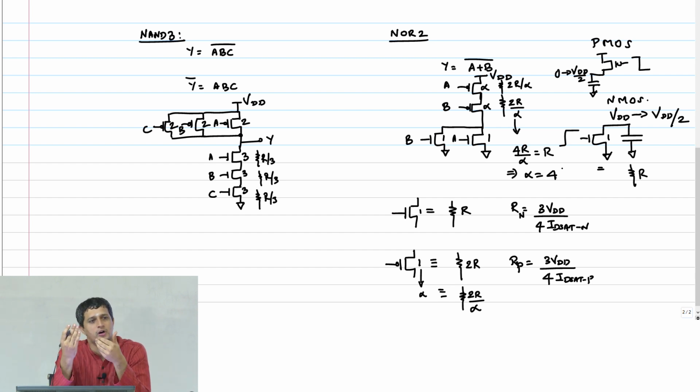So from the inverter, it's not surprising that if you stack transistors, you need to multiply the width by the stacking size, right? So unit inverter is 2, NOR 2 is 4, NOR 3 is 6, and so on. Okay? Any questions here?